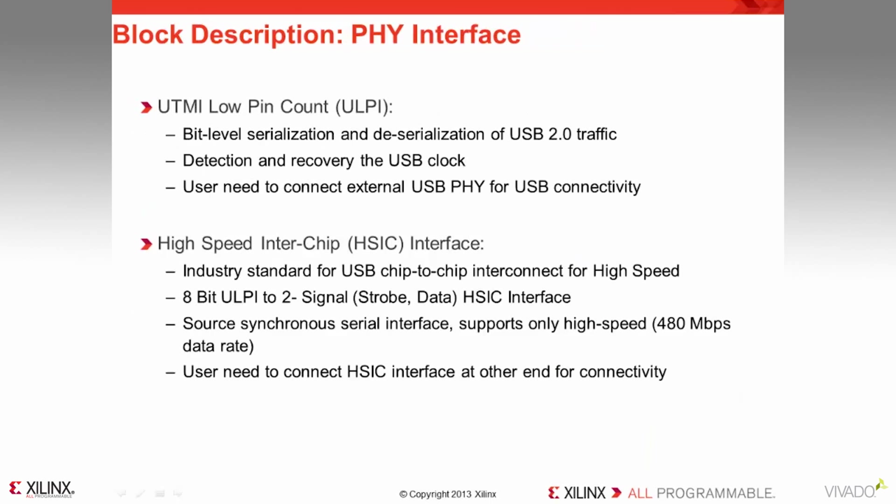On the PHY side, there are two interface options provided by this IP. ULPI, which is the default option. Bit level serialization and deserialization of USB traffic happens. Detection and recovery of the USB clock. User needs to connect an external USB PHY for USB connectivity. So you take the ULPI interface, connect external PHY, and what you get is a USB D plus D minus